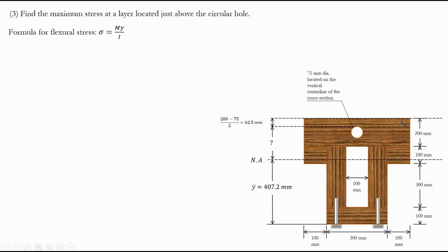For shear, at the edges, you don't have any shear, because shear is not defined there. Shear is a contact of two surfaces. Here as well, shear is 0. And in the neutral axis, you have the maximum shear. You can think of moment and shear as complementary. Force is distributed in a way of shear and normal force, or moment in this case.